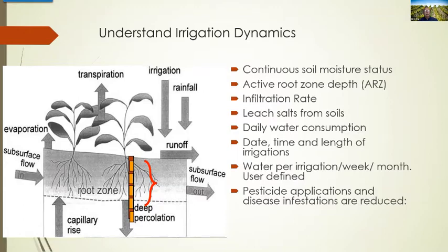What was problematic is that we were irrigating that weaker area, and our good soil that was higher yielding and produced more crop, we were actually over irrigating and probably creating powdery mildew and different disease pressures in that area. So it's really, really critical to understand those soils, not saturate them, and know the emission device that you're using.